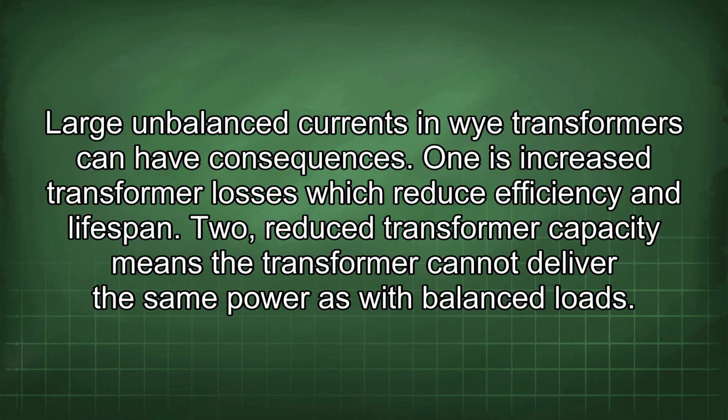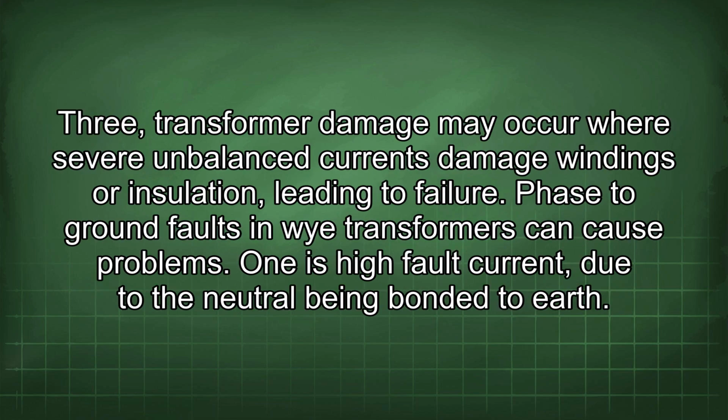Large unbalanced currents in Y transformers can have consequences. One is increased transformer losses, which reduce efficiency and lifespan. 2. Reduced transformer capacity means the transformer cannot deliver the same power as with balanced loads. 3. Transformer damage may occur where severe unbalanced currents damage windings or insulation, leading to failure.